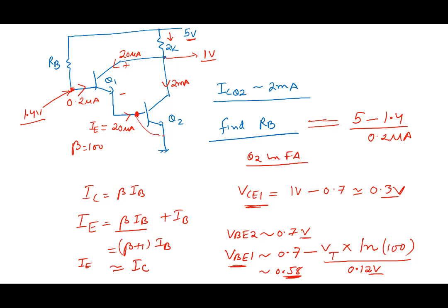In a 5 volt, you're subtracting 5 minus 1.4, or 5 minus 1.3, right? 1.4 versus 1.3 may not result in so much error, but you do see people doing this kind of more accurate analysis by assuming VB1 is this thing as compared to VB2.